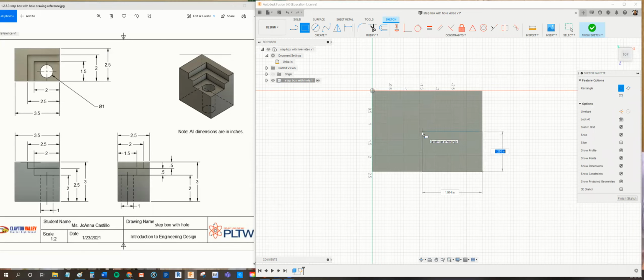And then so the height, right, according to, I'm looking at my drawing here on my left, is going to be, well, looking at from the top view, I'm going to say the right dimension is going to be 2.5. I'm going to hit tab for the next one. And then it's going to be 2.5. Let me hit tab again. This is actually 2. And this one is going to be 2.5. Okay, looking at the reference here, 2.5 across and 2 high. All right. Whoops. Did I mix it up? Okay, so I'm going to left click and then I'm going to finish sketch.